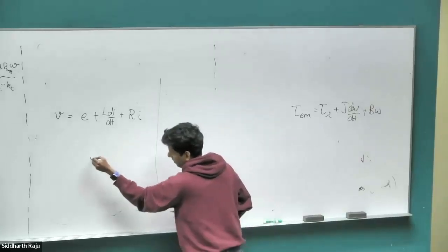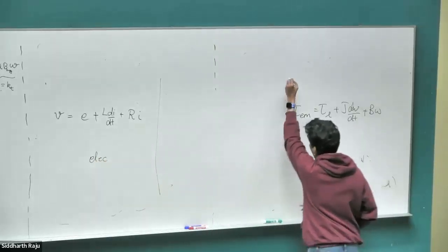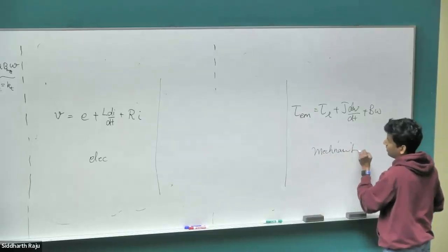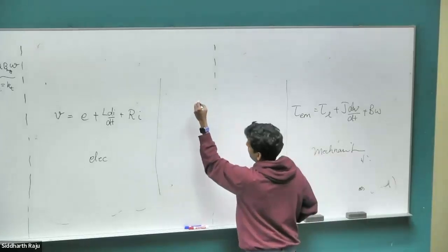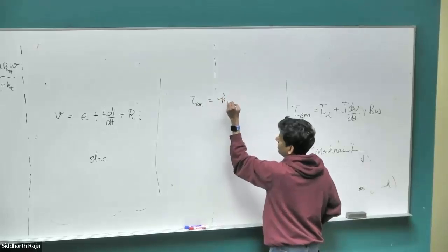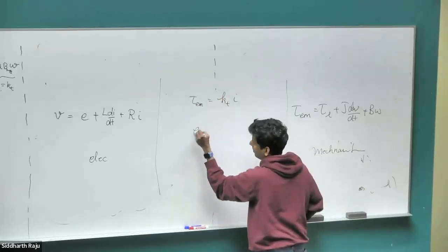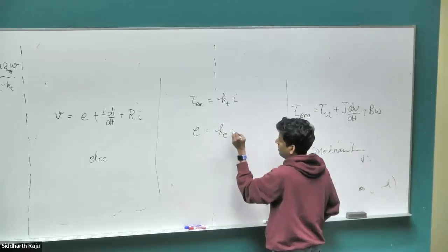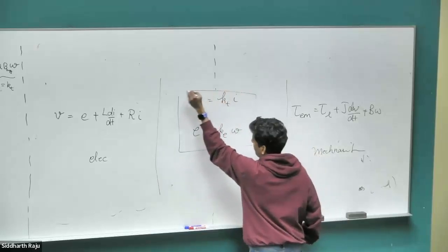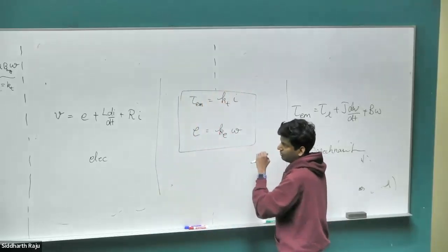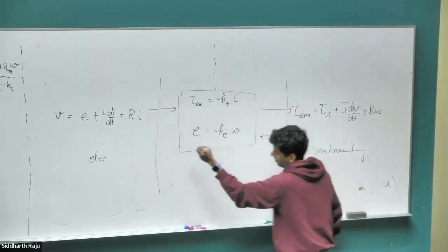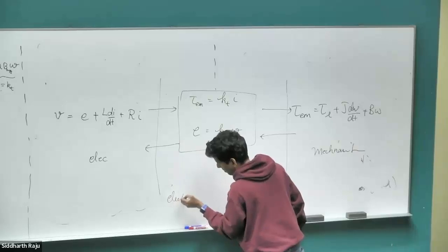So this is the electrical world. This is the mechanical world. They don't like to play together. But then we have our beautiful set of two equations. This is the torque, it is kT times I, and then the EMF is Ke times omega. So all we learned, 2 weeks we spent learning electromagnetic theory is just to get these two equations, right? So that we can marry the electrical world to the mechanical world, so that we can create the electromechanical motor.